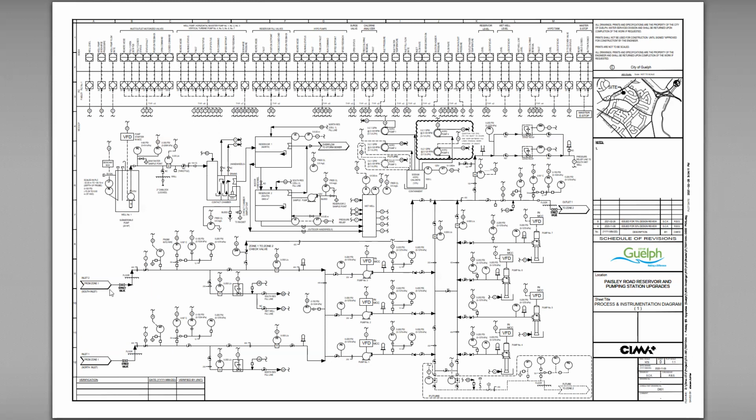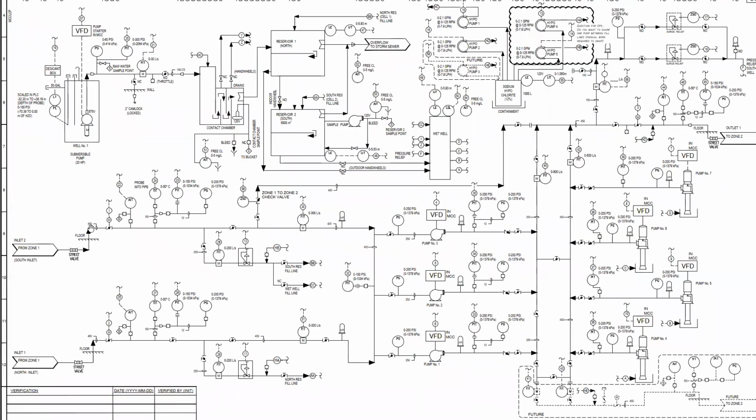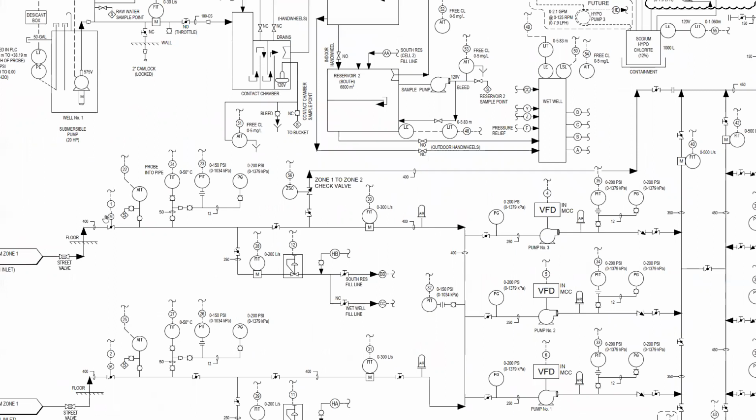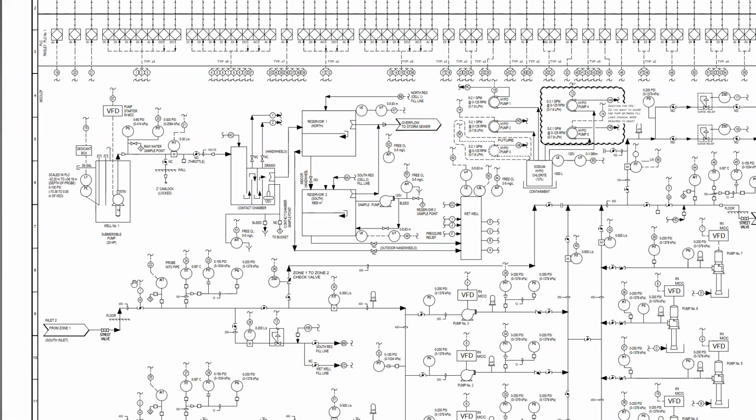So we've got flow coming in here. There's a valve in the street. It's actually indicating that we're coming up through the floor into 400 mil pipe. And now, because there's so much stuff on this drawing, you can see that we're using these squigglies again. So we've got butterfly valve 1 and butterfly valve 2. If you remember from some of the other drawings we're looking at, we've got a butterfly valve, we move up, and we need to find where 1 and 2 go because these squigglies indicate that there's a disconnect.